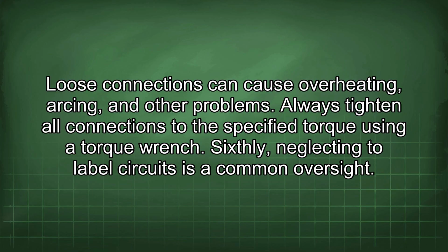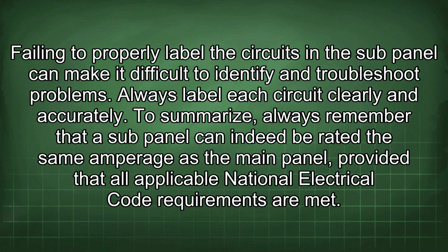Sixthly, neglecting to label circuits is a common oversight. Failing to properly label the circuits in the sub-panel can make it difficult to identify and troubleshoot problems. Always label each circuit clearly and accurately.